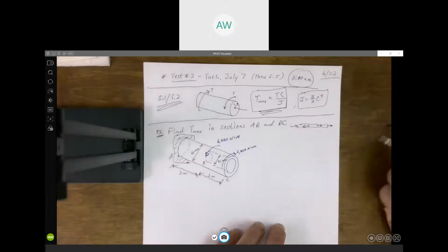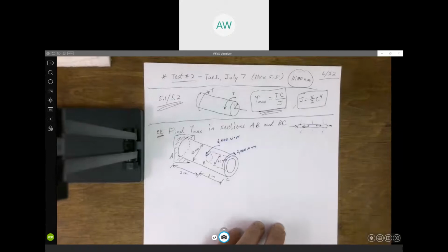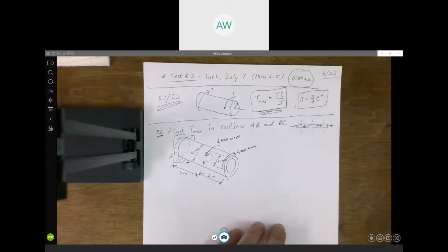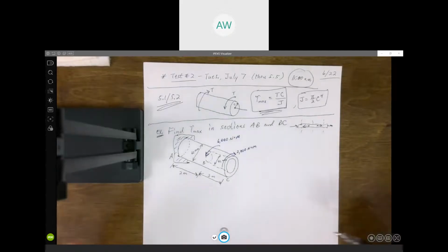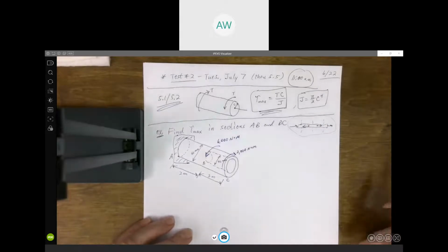And to get the normal stress in each of those sections, we had to do method of sections, come in here and cut it, and find what the axial load was in that particular section in order to do normal stress P over A. Well, the exact same concept works here, except now instead of getting axial or normal load P, we have to get the torque in each section. But how we accomplish that is the same as it was with the axially loaded shaft.